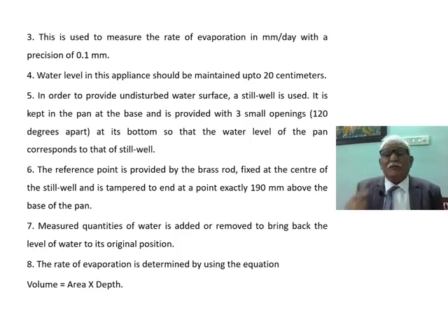When we remove the water, it is because rain has occurred and the level is above that particular point. If evaporation has occurred and the level is below the pointer, we just add the water. So added water is equal to evaporation. On some days, added water plus rain gauge rainwater equals evaporation. On which days this happens, I will tell you in the next two slides.